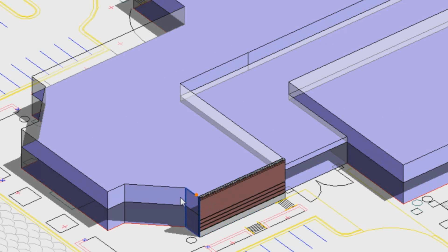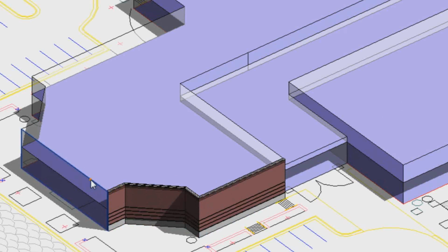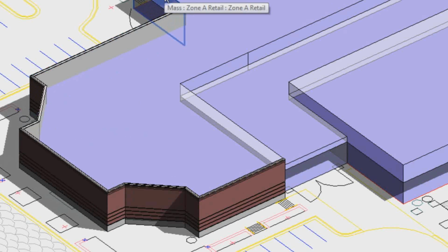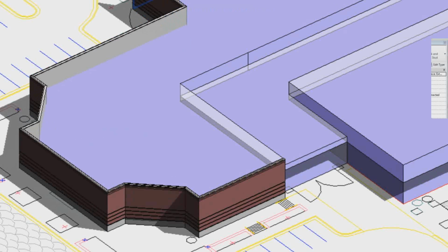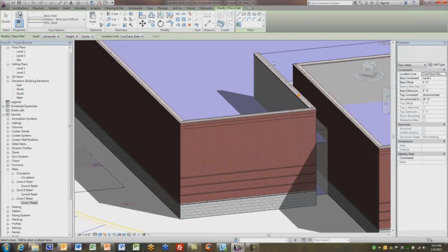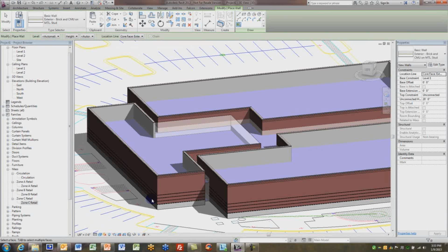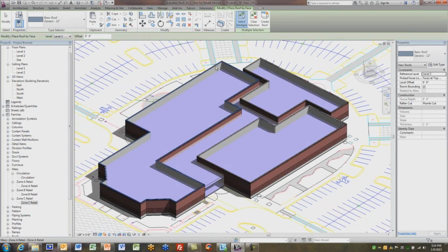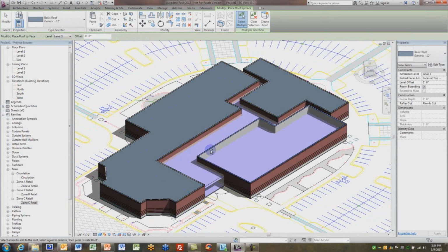Again, by using massing by face, you're able to use building components to attach them to our masses. Since we know the footprint is working, we can just go to the next level and make this a little bit more detailed by looking at roofs, parapets, entrances, curtain systems, and eventually tenant areas and demising walls.